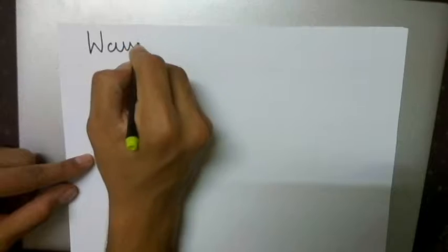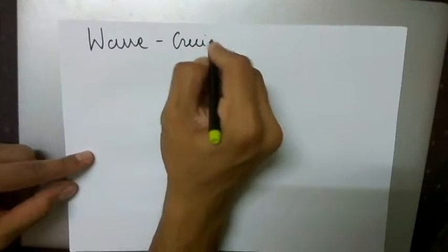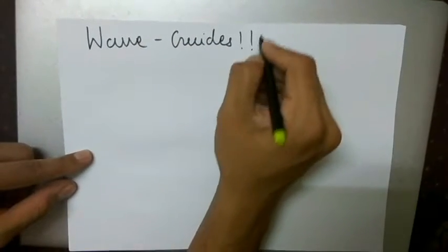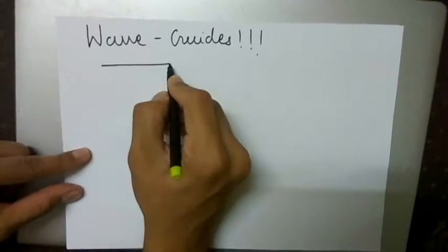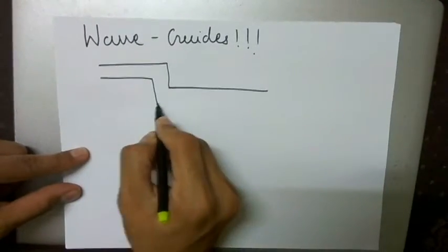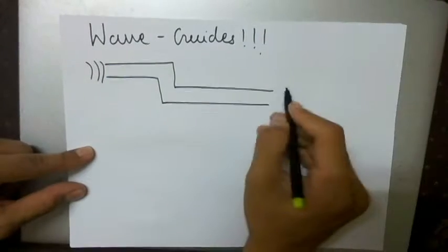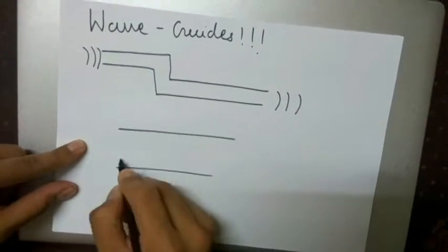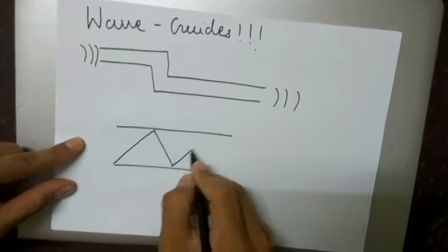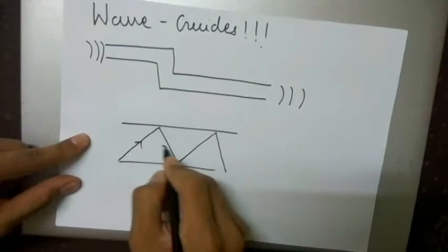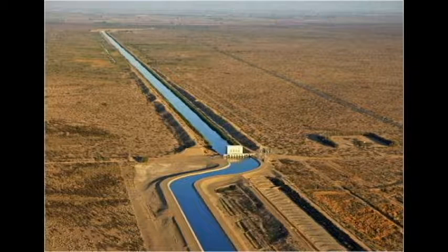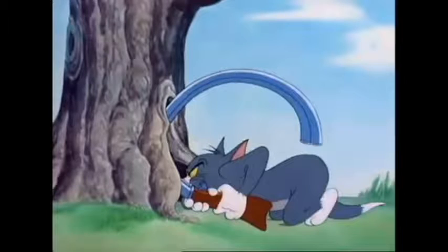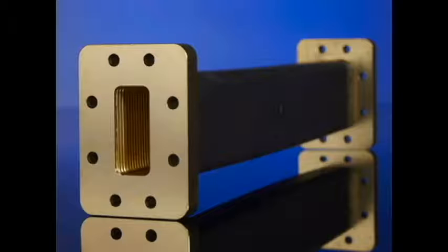So we use waveguides. A waveguide is a structure that guides waves such as electromagnetic waves or sound with minimal loss of energy by restricting expansion to one dimension or two. A waveguide may refer to any linear structure that can convey EM waves between its endpoints. The EM waves in a waveguide can be imagined as traveling down a zigzag path, being repeatedly reflected between the walls of the guide. This is a similar effect to waves of water constrained within a canal, or why guns have barrels that restrict hot gas expansion to maximize energy transfer to their bullets.